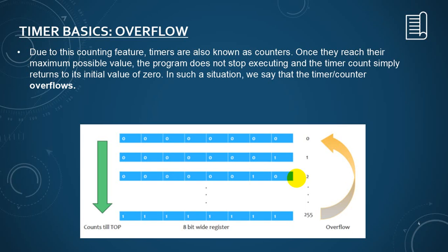When there is an overflow, it sets a bit in the flag register. So you check the bit. There is an overflow, one count, another overflow, another count. So it is easier. Just check a single bit and you know how many counts have been made. This is one technique of counting. That means you can get different time lengths because you are changing the cycle time by dividing the main clock frequency with the prescaler.